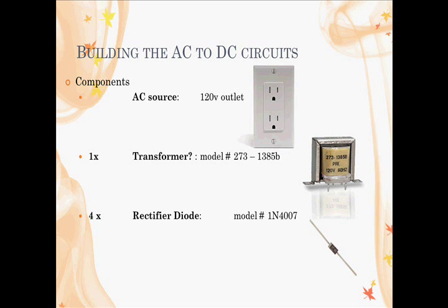And the transformer we recommend if you're going to be doing this is model number 273-1385B. What this transformer does is convert 120 volts AC to 12.6 volts AC. And if you're going to be using another transformer, refer to its manual for its operational load.